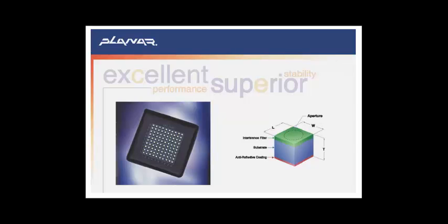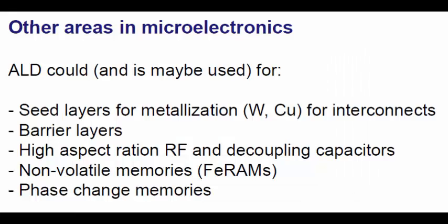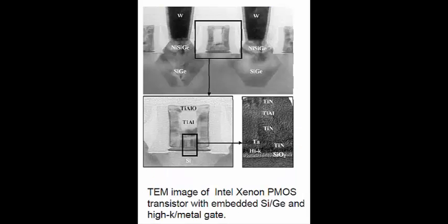ALD has even microelectronic applications in depositing gate oxides, the deposition of high K oxides like aluminum oxide, zirconium oxide, and many others.